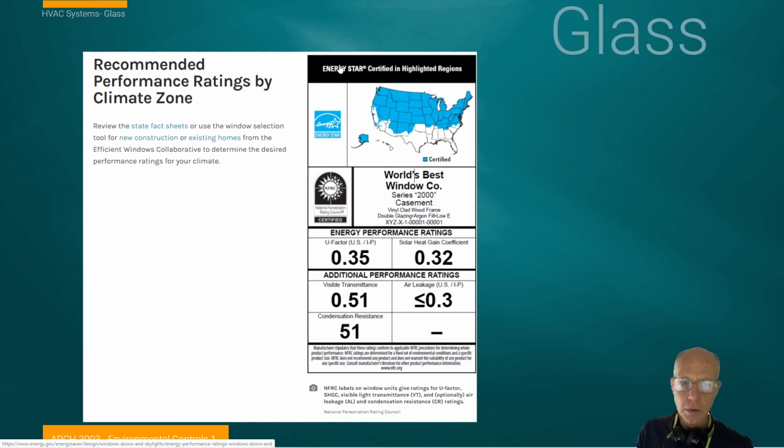So this Energy Star certification you'll see attached to many of the glazing systems, especially at the residential level. And it describes, and this is very interesting, for instance, what climate it's recommended for. So here we have it certified as an Energy Star performing glazing system in this climate. This is because it's probably a predominantly cooling climate, and it's not certified for here because this window is not designed to be performing in a warm weather climate, and because we would have opposite performance criteria for it.